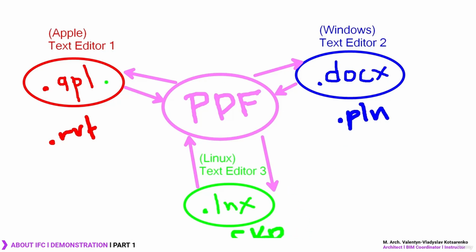But what the three different BIM platforms, also considering SketchUp a BIM platform, share in common is that they will have the possibility to export everything into the IFC format, and you can import the IFC into SketchUp, you can import IFC into ArchiCAD, you can import IFC into Revit, and vice versa. Revit is able to export in IFC, ArchiCAD is able to export in IFC, and SketchUp will be able to export in IFC, which is completely amazing.